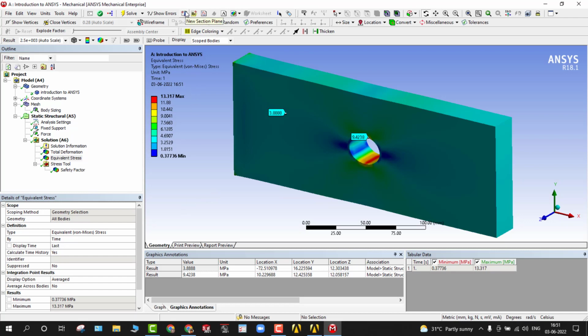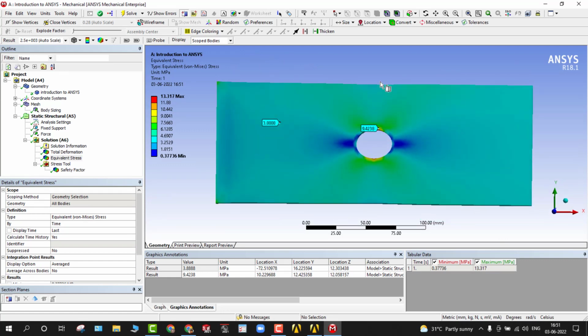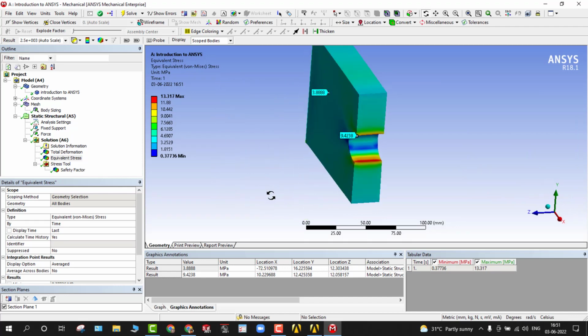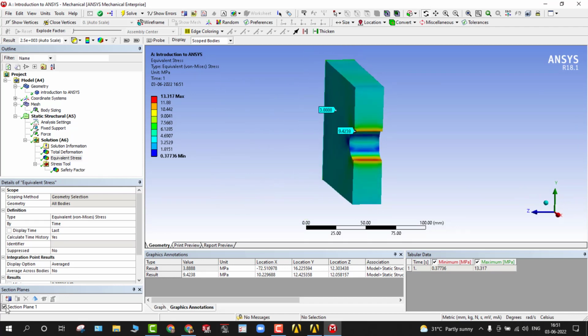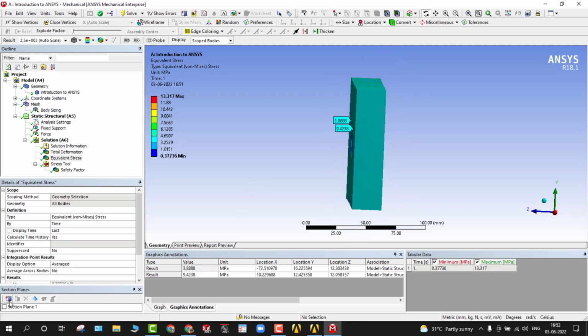Yeah, so this is the new plane section view. So from here you can simply drag a line to just cut it. We could see the preview. Okay, you can uncheck this, or if you want to delete that, you can even delete it. So I want to create a new plane. I'll simply cut this one like this.